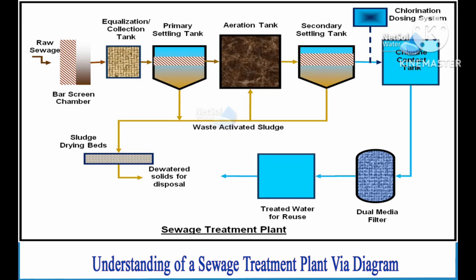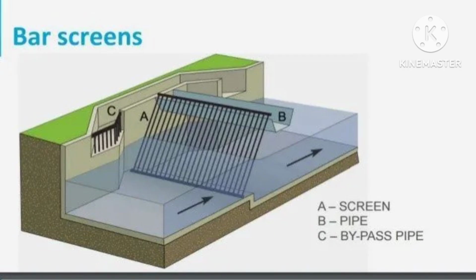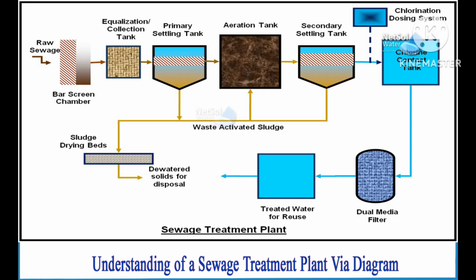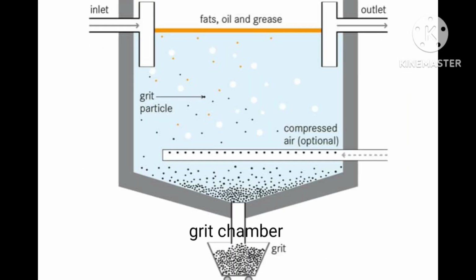Thank you. The first stage of treatment and processing of wastewater is bar screening. Large objects must be removed from the effluent to avoid harming the facility's pumps, valves, and other components. The hope is that after treatment, the water will be safe to re-enter the environment. The next stage is grit removal, by passing effluent over or through a grit chamber. This is to avoid harming pumps and equipment downstream. Fine grit that enters the influent must be eliminated.